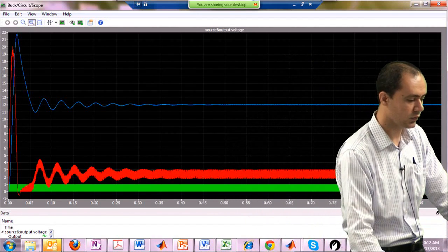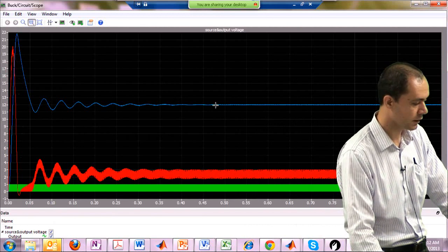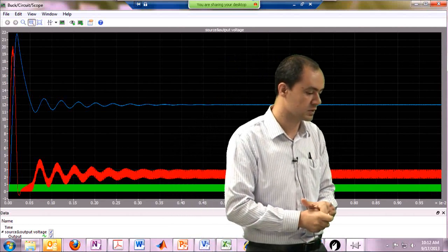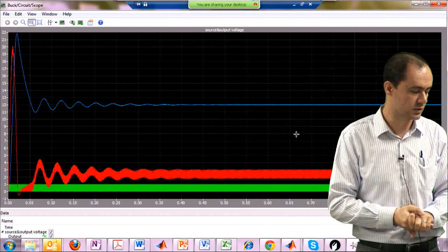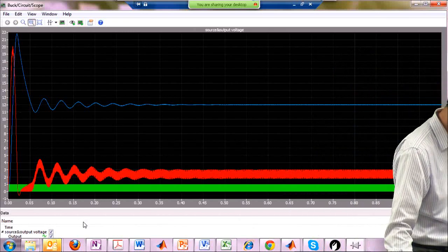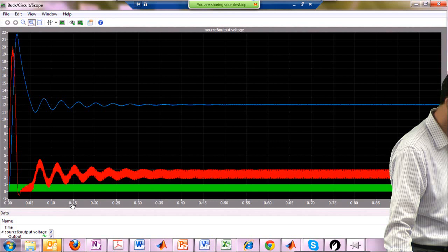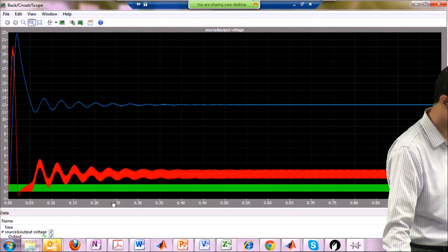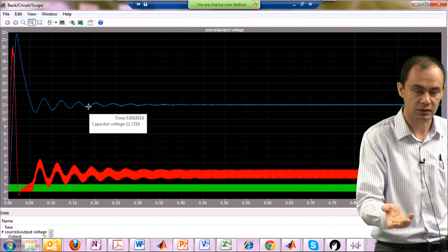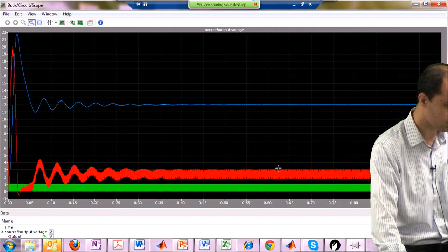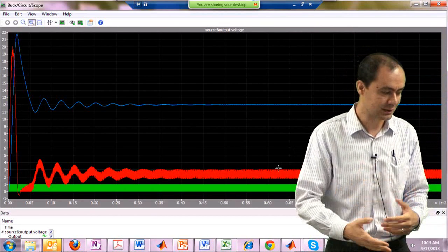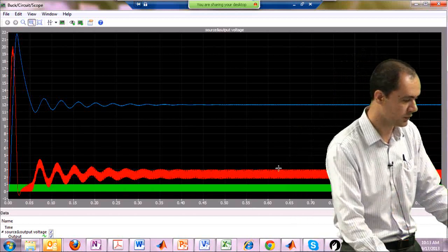So we have to zoom in on this area instead of this area. Now you will be surprised, even in a graduate level class, you assign students to run some simulations, and they get different final results. The reason is they haven't run their simulation to reach the steady state. For instance, if you choose the end time of your simulation to be 0.15 times 10 to the power of negative 2, your final result is going to be here, and because you have not reached the steady state, your final result may not reflect the reality of the steady state operation. So please remember, whenever you are simulating a power electronic converter, run it long enough so that a steady state is achieved. Very, very simple. A lot of people forget about that.